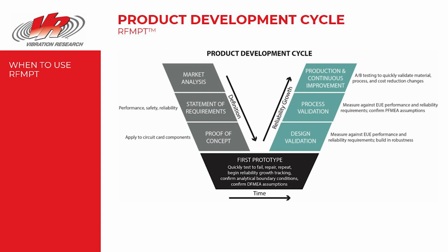Here it can be used to root out obvious design flaws, confirm upper and lower environmental operation points, and to establish what the destruct limits are for the design. This should be done early and with a relatively small number of parts on test and repeated as failures are identified and proposed solutions evaluated. This is also a good time to test just elements of a system, such as a circuit card or a cooling loop seal design.